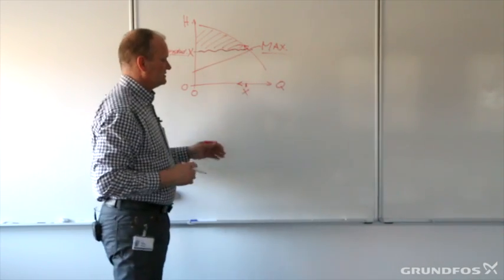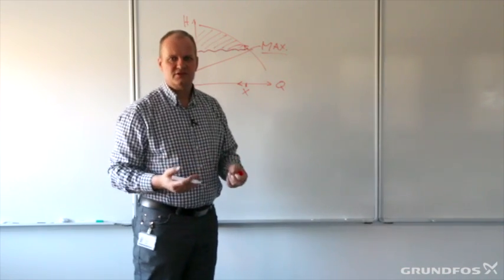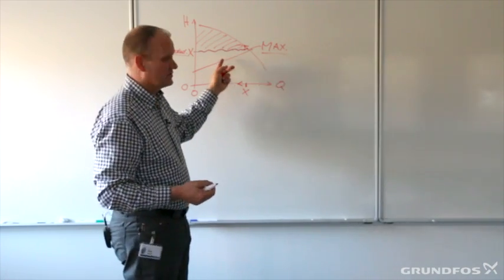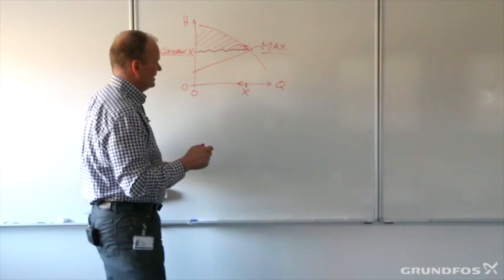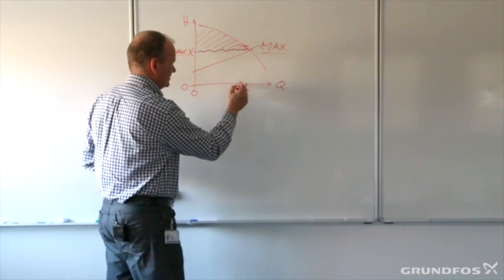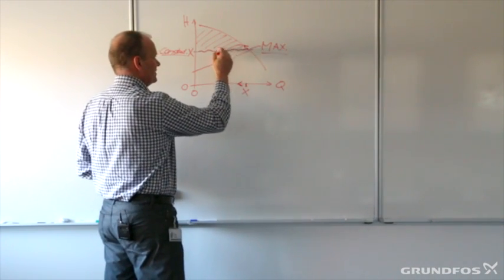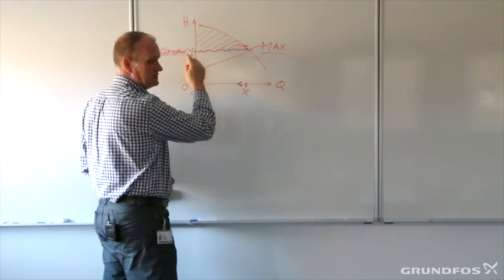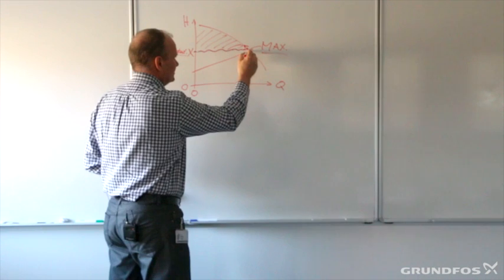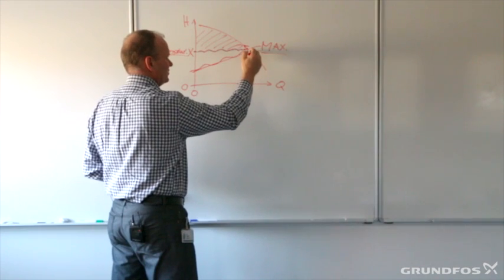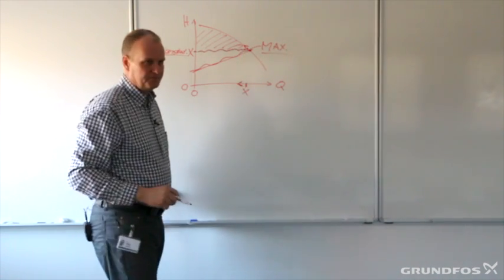And what that means is that it's just the next generation of constant speed or constant pressure, so to speak. And what it does is that when the same valves again are closing, instead of providing the system with constant differential head here, it reduces the head according to the set point, which is out here.